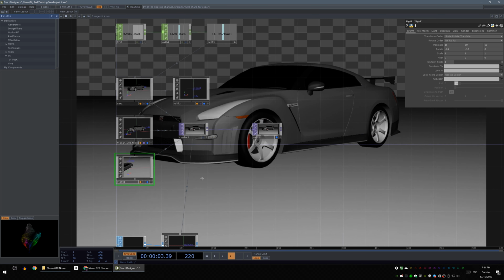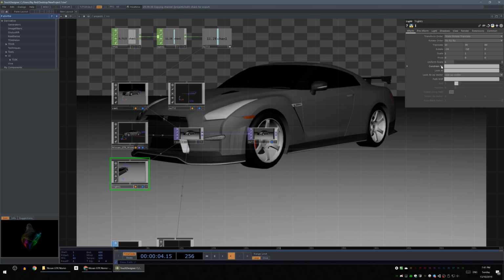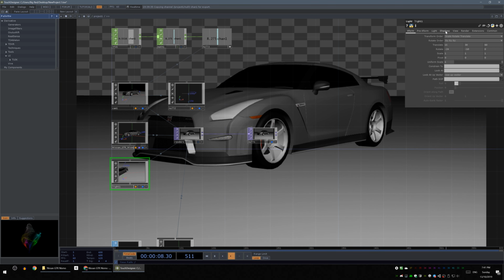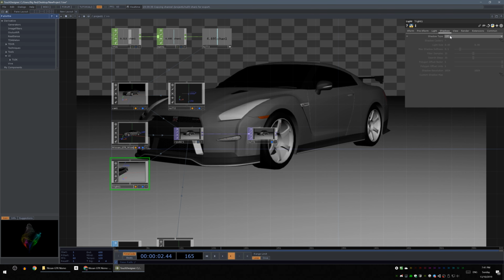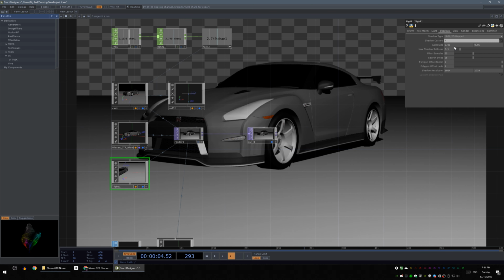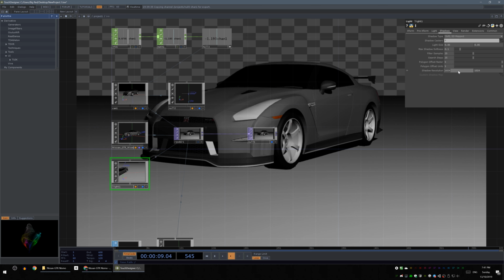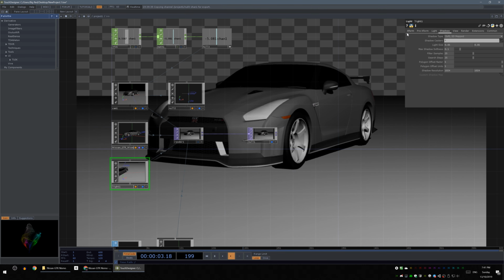And the next thing we want to do is have the light looking at... no, we'll leave the light there for now. The next thing we want to do is go to shadows on the light parameters and change the shadow type to soft 2D max, and then down here in the shadow resolution we want to increase that a little bit, because you'll see if I move this light,